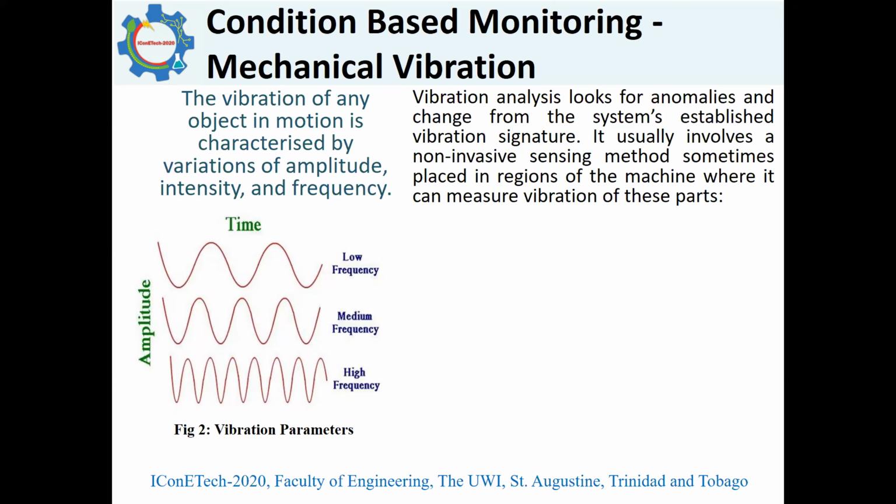So in order to know that, we have to have some kind of baseline for a vibration. And ideally, a baseline is taken new out of the box as you install it. You take that vibration signature so that afterwards, your trending always has something to reference back towards. Now, in most cases, there are systems that are installed for years upon years. So we can look at, after a motor or a generator has been serviced, taking that point as our baseline if we are looking at an older system.